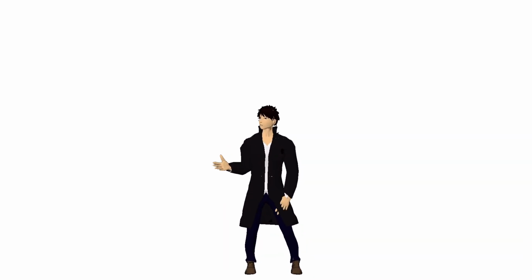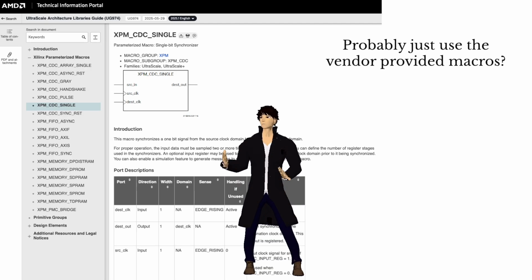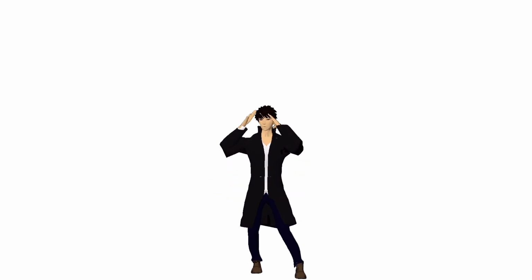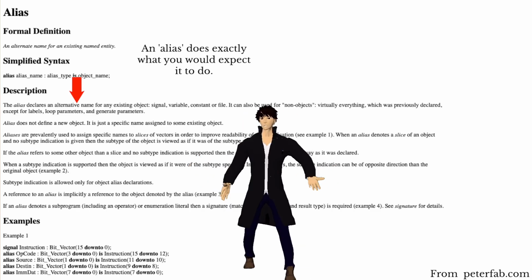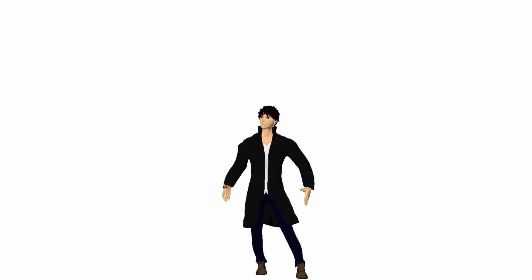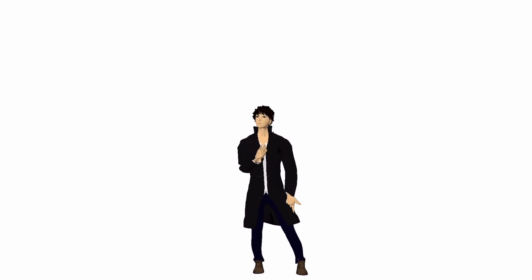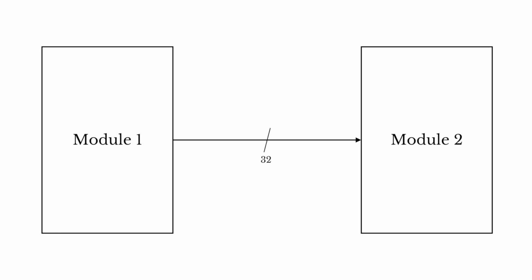If you're working with an FPGA, there's most likely a recommended number of stages to use. Or you have no clue what the original designer was thinking because he used an alias to connect a data signal between clock domains. So you just use a 2 flip-flop synchronizer. Which reminds me, data buses are a bit special. Multi-bit buses are a bunch of single bits that are related to each other. Obvious, so what?